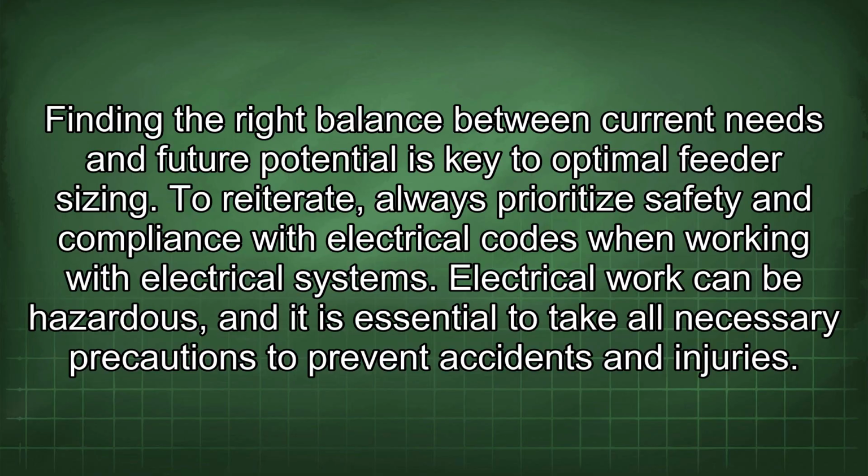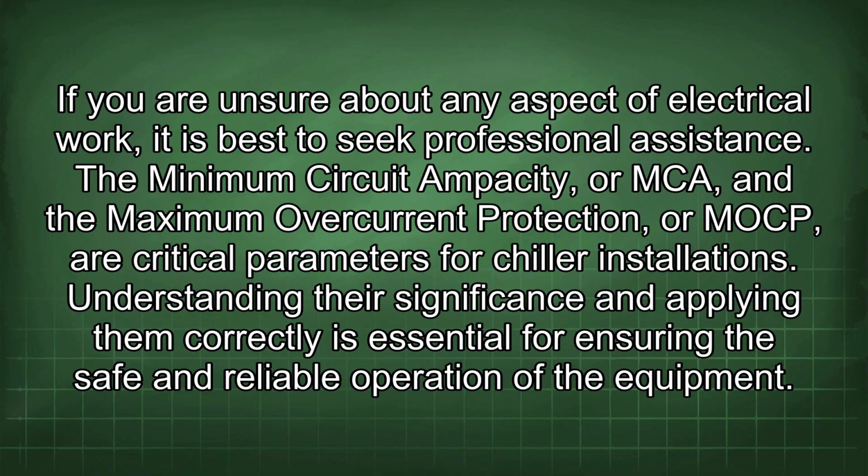To reiterate, always prioritize safety and compliance with electrical codes when working with electrical systems. Electrical work can be hazardous, and it is essential to take all necessary precautions to prevent accidents and injuries. If you are unsure about any aspect of electrical work, it is best to seek professional assistance. The minimum circuit ampacity, or MCA, and the maximum overcurrent protection, or MOCP, are critical parameters for chiller installations. Understanding their significance and applying them correctly is essential for ensuring the safe and reliable operation of the equipment.